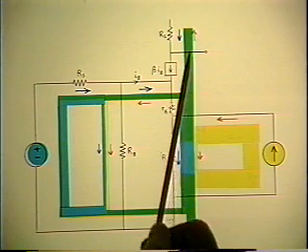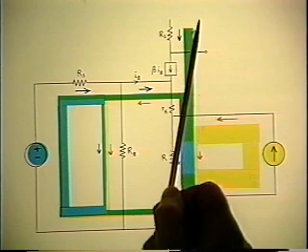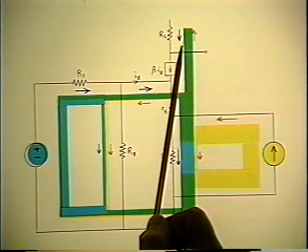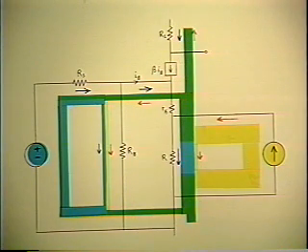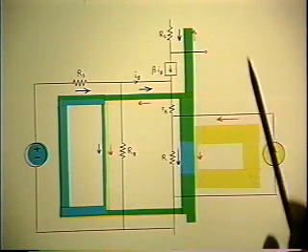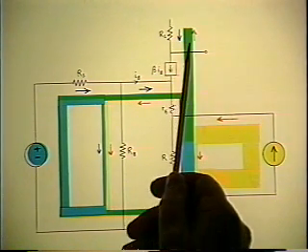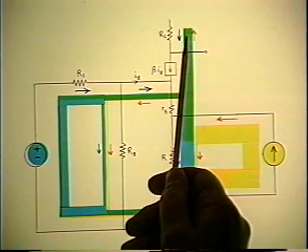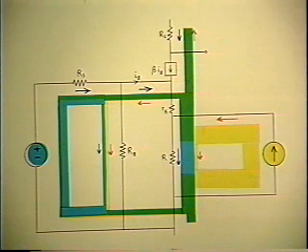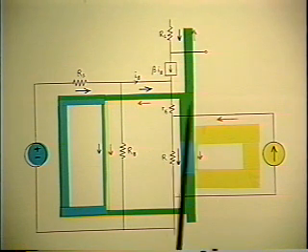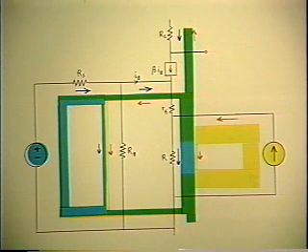And you see what has happened is that if you look at these two arrows, the blue arrow is down, the yellow arrow is up, and they're equal in magnitude. This is how you get the null. You've made those two currents equal and opposite by appropriate adjustment of those two sources. So they cancel out. That's how the null develops. And you see the propagation of the null now becomes obvious. Because the only way you can get a null at the output of the transistor is to have a null at the input as well.